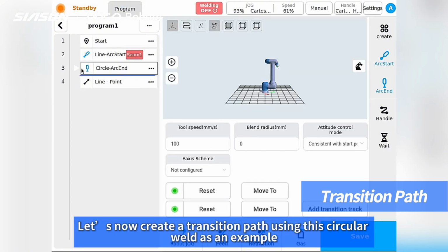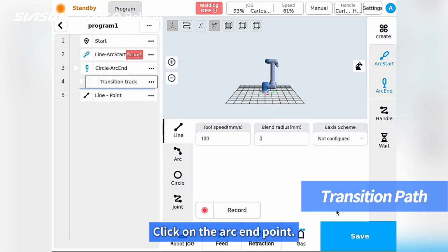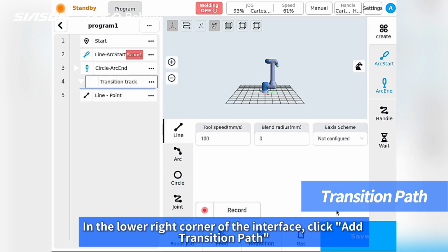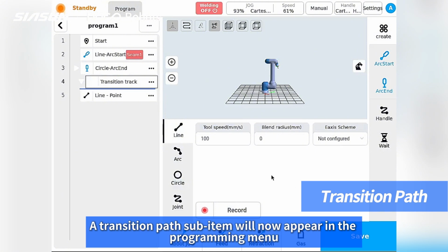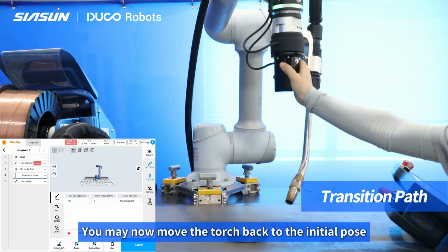Let's now create a transition path using this circular weld as an example. Click on the arc and point. In the lower right corner of the interface, click Add Transition Path. A transition path sub-item will now appear in the programming menu. You may now move the torch back to the initial pose.